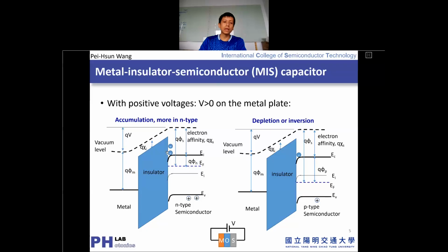However, the band structures will alter because we get the electric field. So in between the carrier accumulation region or the junction region, you can see the same slope of this function, and this slope equals to how much electric field we can have. And the more voltage you applied, we get a stronger electric field, and we get an abrupt slope for this junction layer. And then after this bending, you may notice that the Fermi level will still be flat.